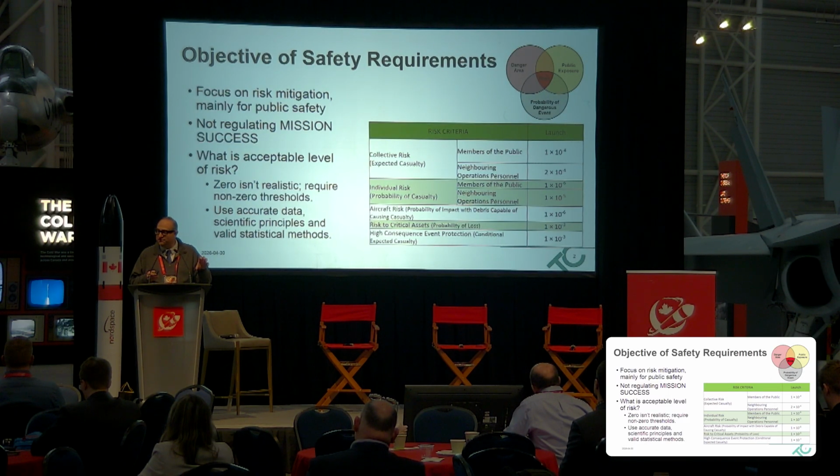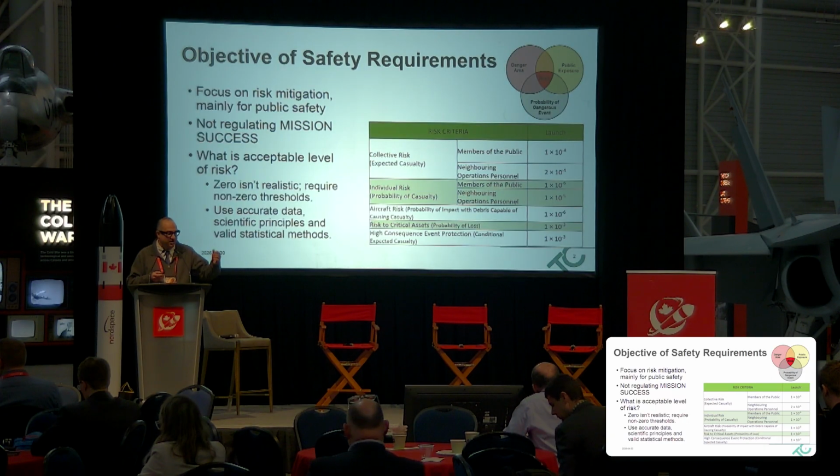But once there's a failure, a danger area ensues: toxic release, debris, inert or explosive, or it could be overpressure. Then the next piece is, there's a hazard area, so are there people there, or is there an asset there? If there's no asset, then there's no risk. So any of those things being zero gives you zero risk, but there's a little bit of all of them in play, so you usually get some number. That's how risk is defined.